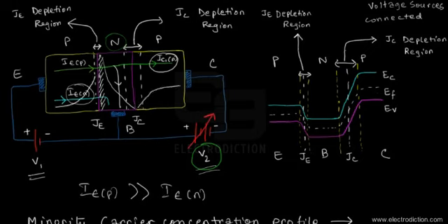Okay, so let's put numerical quantities over here so that it's easier for you all to understand. Let's consider that V2 is kept at, let's say, 5 volts for now, and due to this we have a base width, or rather this depletion region width over here, of, let's say, W1. Now if we just increase this to, let's say, how much?